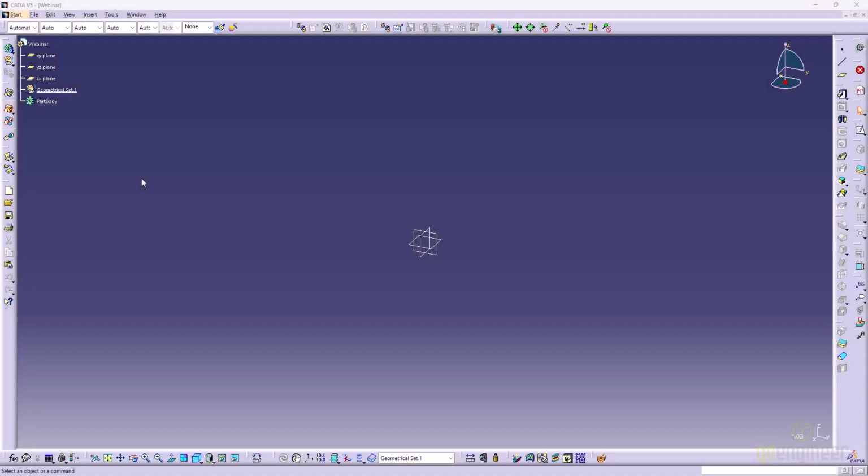Looking at the CATIA user interface, one item that is difficult for new users is the specification tree. The specification tree has a few quirks, including hiding, tree customization, and expanding and collapsing, which are typically struggles for new CATIA users. Sometimes new users hide the specification tree and have no idea how to get it back. CATIA has a keyboard shortcut, also called a hotkey, to hide or show the specification tree. When users accidentally hit F3, the specification tree disappears and is no longer visible, even in hidden space. To bring the tree back, users must hit F3 again, or go to the View menu and click on Specifications.